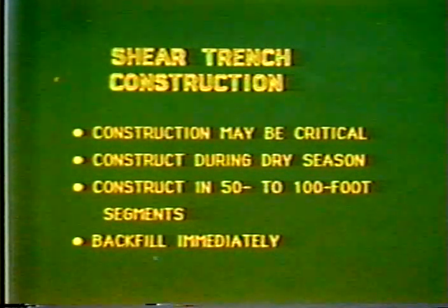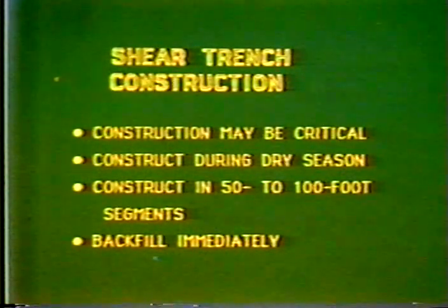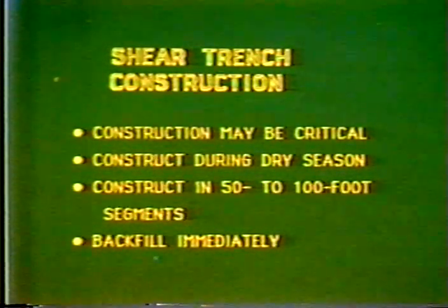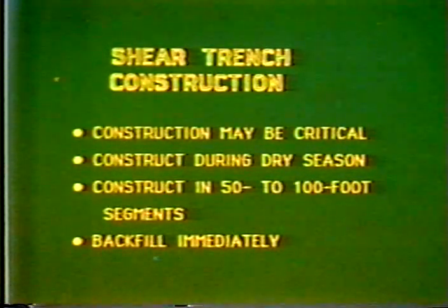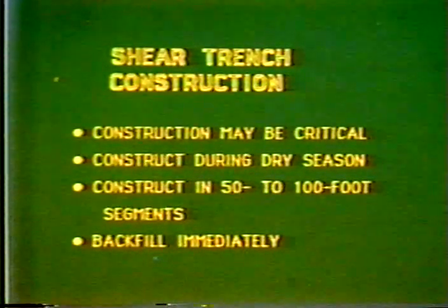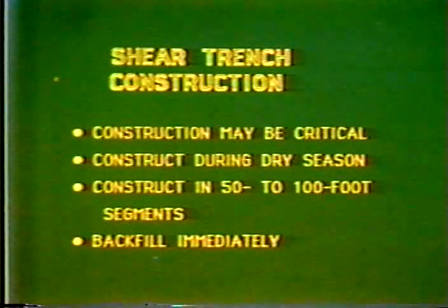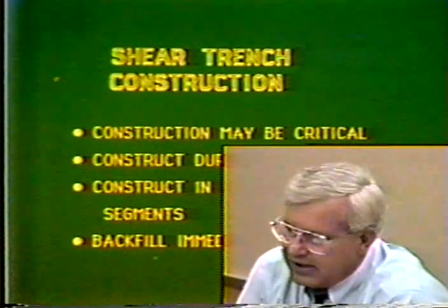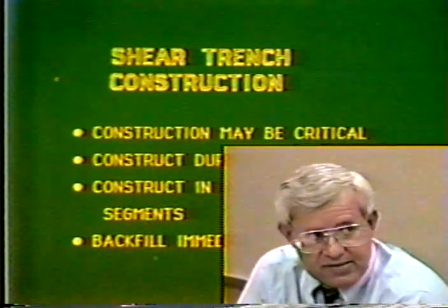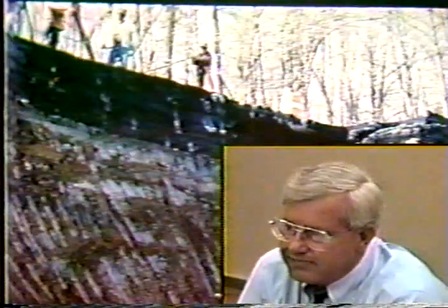And it's good to construct it, as I want to emphasize again, in short segments. As soon as you construct a short segment, you excavate the material, backfill the rock, and put the rock back in quickly, as fast as you can. In other words, if you have to have 4 tandem trucks parked there with stone waiting to place the material, do it. So I'd like to emphasize the last point there: backfill immediately.